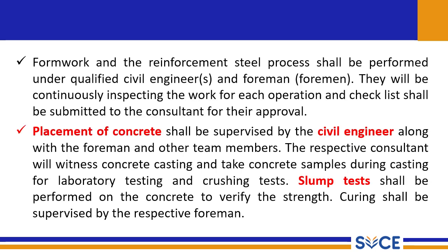The formwork and the reinforcement steel shall be performed under qualified engineers and foremen. They will be continuously inspecting the work for each operation, and the checklist shall be submitted to the consultant for their approval. The placement of concrete shall be supervised by a civil engineer along with the foreman and other team members. The respective consultant will witness the concrete casting and take concrete samples during casting for laboratory testing and crushing testing. A slump test shall be performed on the concrete to verify the strength.